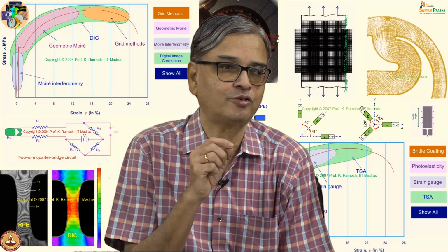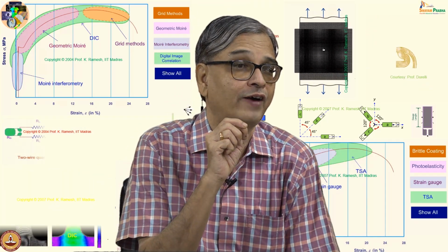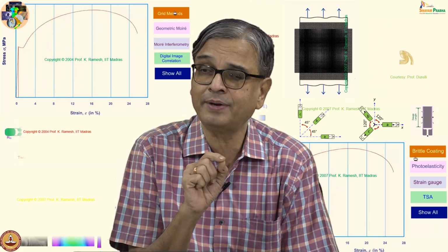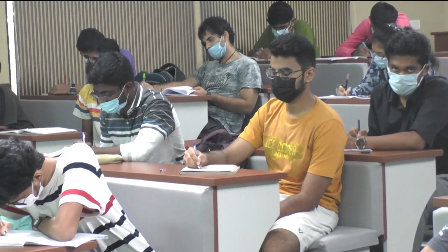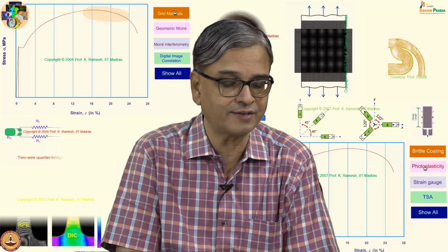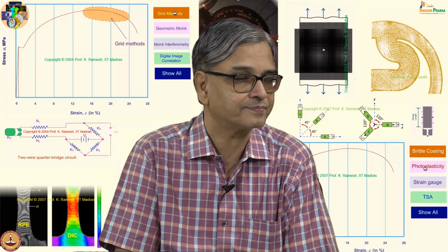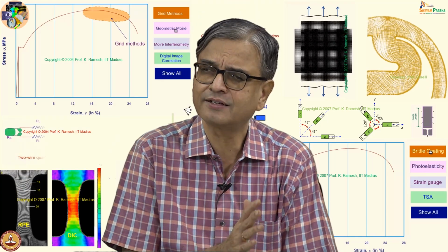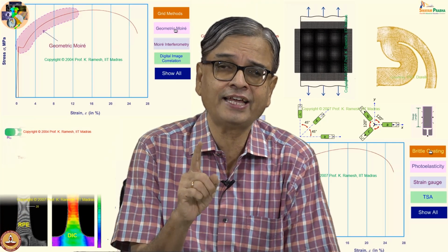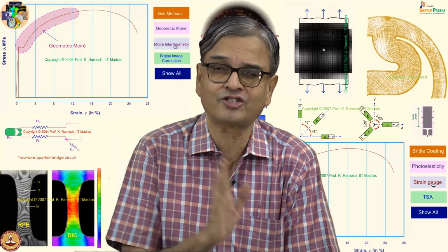First thing is you should know how to find out what is the load applied on the system. So, you take a square element, draw the strain or stress acting on that, whichever way you can do it. Make a mistake, no problem. And I have already told you a strain gauge can measure only axial strain.